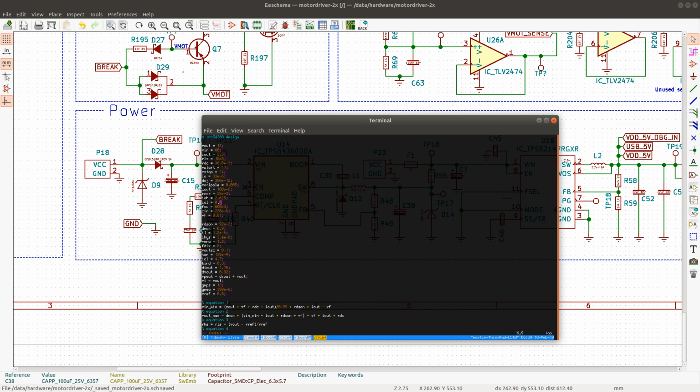I think so. When I'm designing this board for revision A, I don't actually know the minimum and the maximum output current. That's going to need to be measured. So I'll just keep the values that they have used in their application. I'll first try to run it with these values, and then I'll try to reduce the low limit and maybe increase the high limit a little bit and see what happens to the calculations.